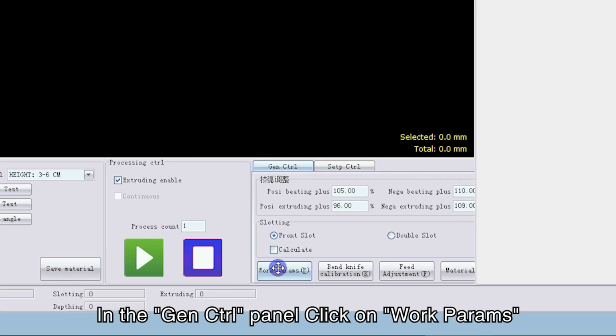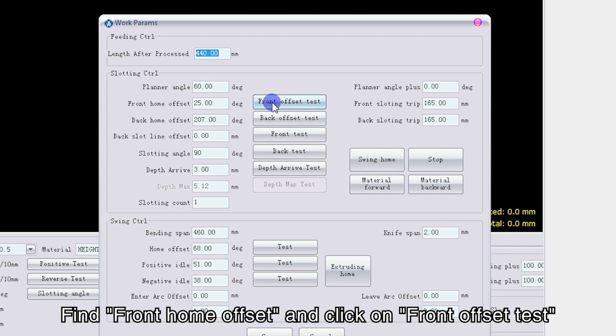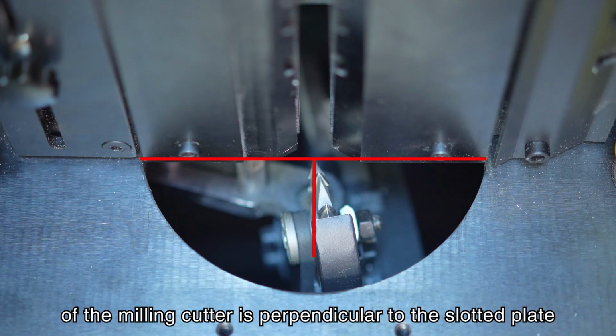Fourth, Work Parameters. In the General Control panel, click on Work Params. Find Front Home Offset and click on Front Offset Test. Observe and determine whether the swinging position of the milling cutter is perpendicular to the slotted plate.